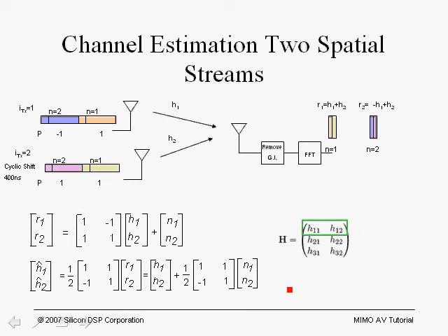So clearly we have obtained estimates of the channel frequency response at that carrier, H1 and also H2. For example, if we assume that the noise is 0, this term drops out, and we get that the H1 estimate is equal to H1 and the H2 estimate is equal to H2. Of course, we do have noise, so there is noise in the estimates of the H matrix.